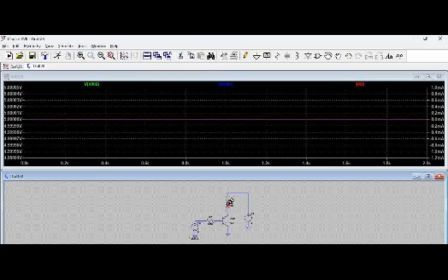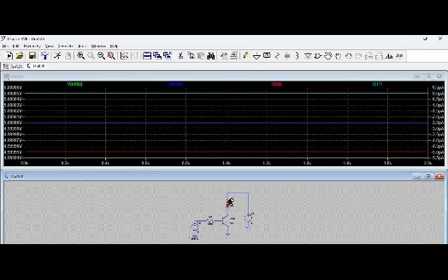And then if you try to probe the current here, that also is a negligible value of 0 amps. Now this indicates that this particular transistor, with the given operating conditions, is in cutoff region, and there is no current flowing across any of these terminals.